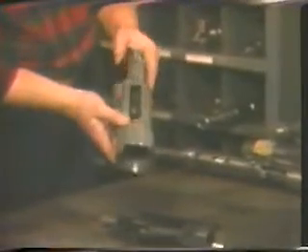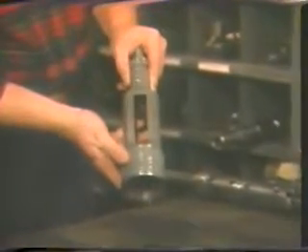In addition to the specialized subsurface production controls run into the tubing with this work string, there are several other commonly used tools which may be run for routine operations. For example, the first step in performing any wireline operation downhole is to determine if the tubing is clear to the depth at which that operation is to take place, and if not, to clear any obstruction from the tubing. This is the function of the tubing conditioning tools, which are normally part of the service equipment used by the wireline specialist.